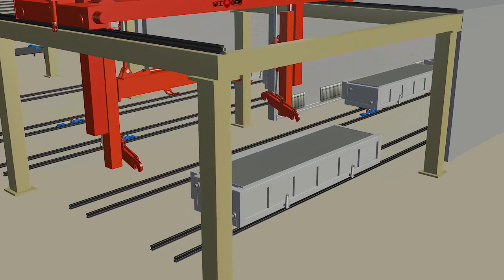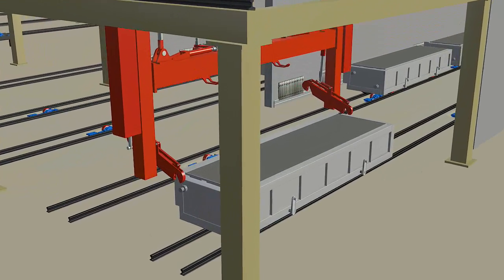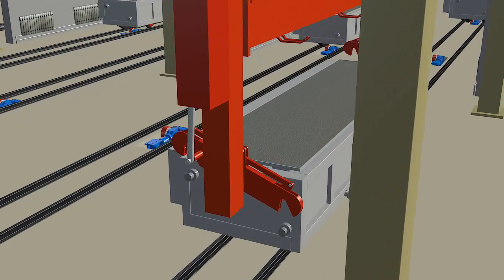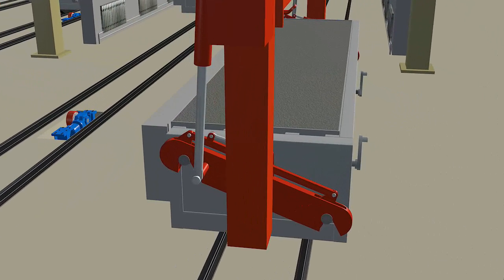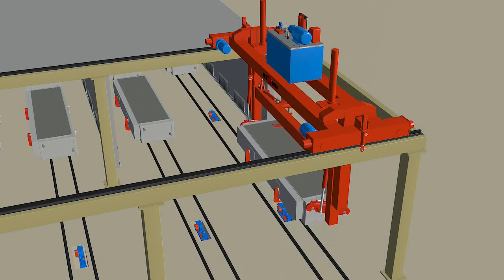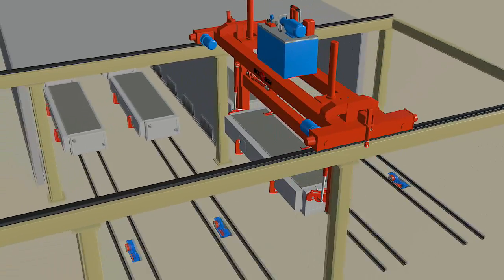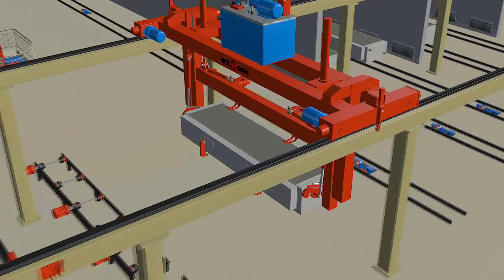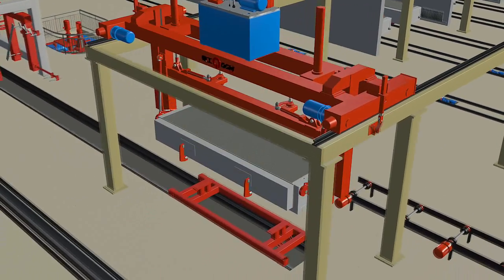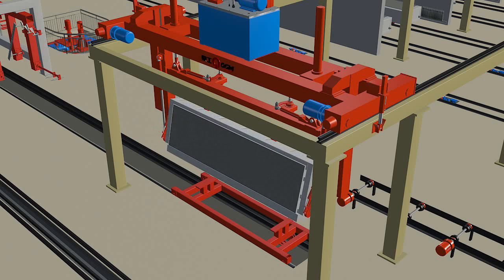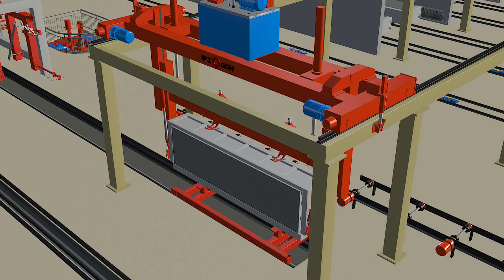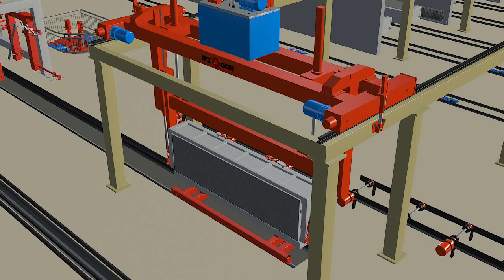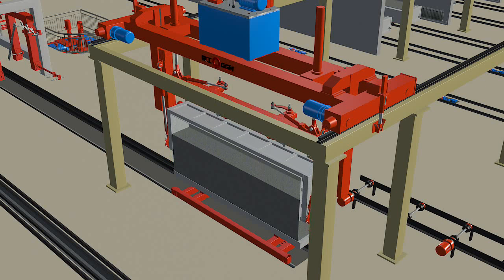The mold with the casting cake is transported to the cutting zone by a turning hanger with automatic positioning, and put onto the loading car after 90-degree overturning. Then the manipulator separates the cake from the mold.